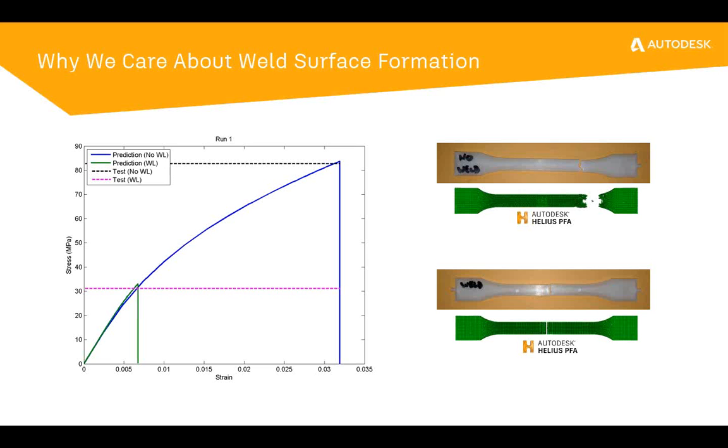So we'd expect these simulation results to be quite close. But what's really important to focus on is that when we applied the knockdown factor for this particular material, we got the green curve. And so just by applying the knockdown factor for this butt weld, we were able to, again, very closely predict the simulation, the resultant strength of the material when we compare it against the experiment.